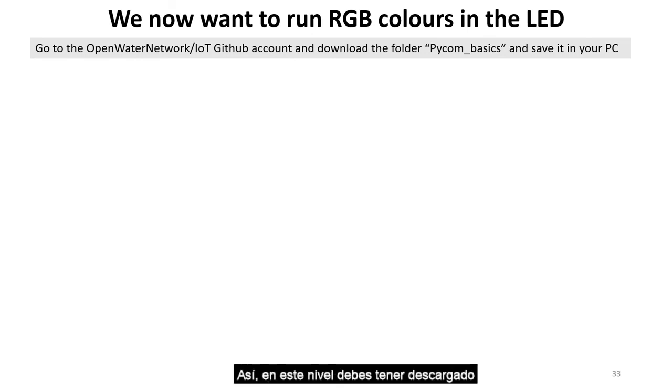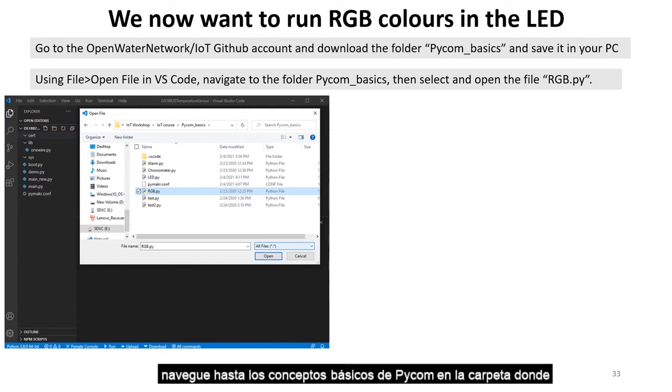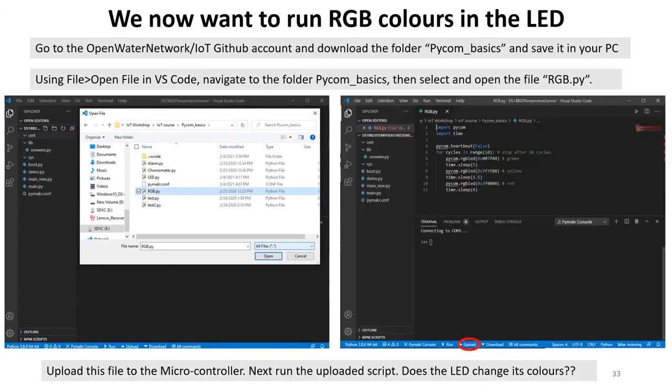By this level, you have downloaded the file PyCom Basics and saved it on your PC. You may have downloaded it from our GitHub account, or you may have received it from a different source. But what's important is that you have the PyCom folder saved on your PC. Now, open Visual Studio Code and navigate to the folder PyCom Basics where you have saved it. Then select and open the file rgb.py. Once you've opened the file, go ahead and upload it as indicated below.